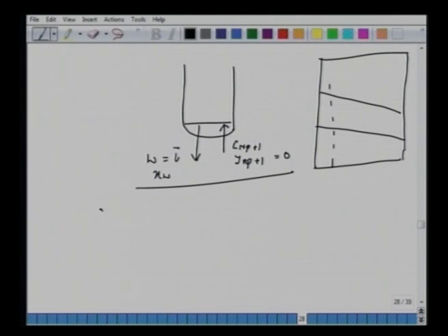So what are the definitions for x delta W? Again, whatever is leaving from the bottom product, which is nothing but W xW, over the net molar flow rate, which is W minus G_{NP+1}. When you put this as 0, it gives you the same as what we had before. Now the composition of this hypothetical stream leaving the system is W xW by W minus G_{NP+1}.